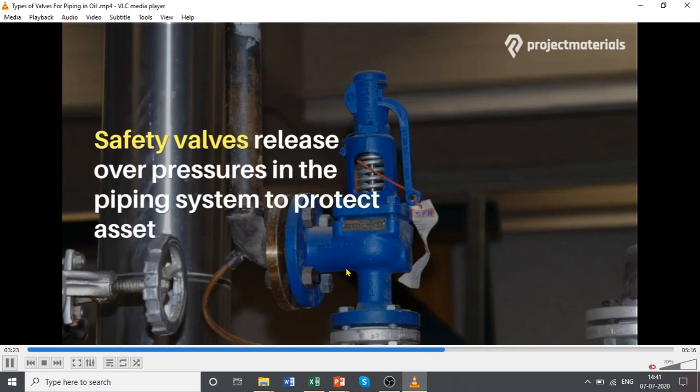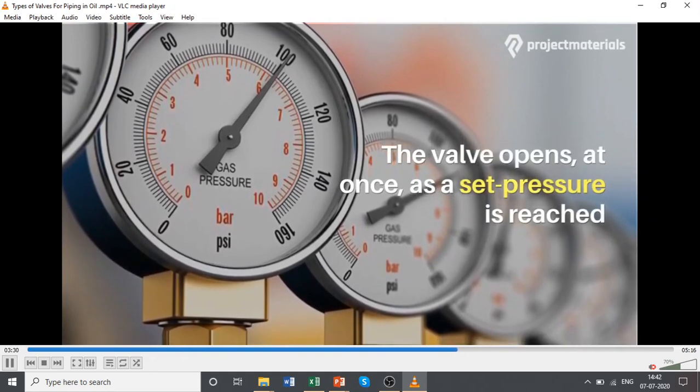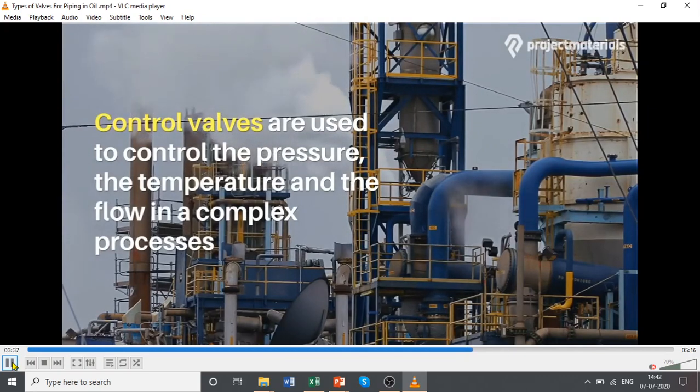Safety valves release pressure. They open only when a particular pressure is exceeded. So if you set a pressure relief valve to 10 atmosphere, let's say, then if the pressure becomes 9 atmosphere, 9.99 atmosphere, it will be closed. But if it exceeds 10 atmosphere, say 10.1, 10.2 atmosphere, it will allow material to go out and protect the reactor or whatever process equipment you have. Allow the liquid to go out, gas to go out.